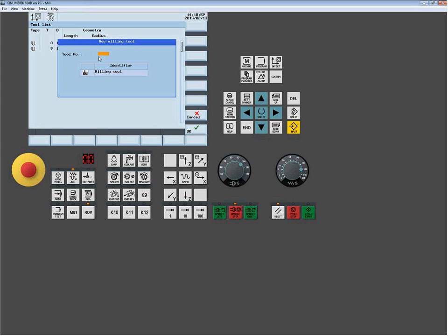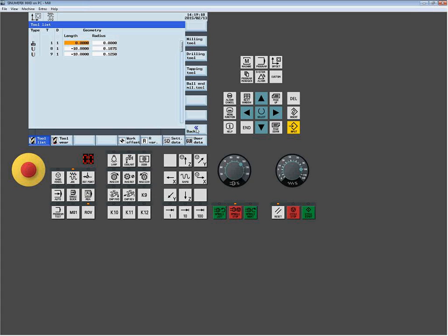the tool number. Now this would probably be one of the first things you're going to see that's a blaring difference between the 808 and some of our more advanced controls like the 828 and the 840. And that's the fact that in the 808, you can only assign tool numbers as names. When you get to some of the other controls, you can actually get a little more creative in your naming terminology.